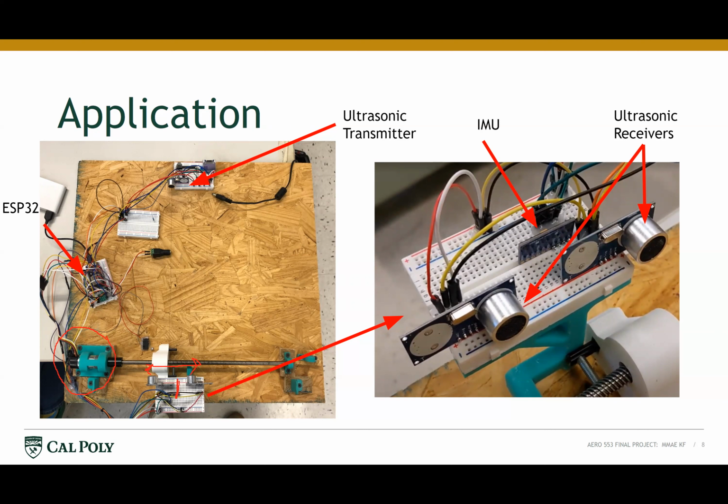And then the two methods we're using to estimate position, which are more realistic, like having a car driving down a road where you don't know the true position because it's not attached to a linear screw, are, one, acoustic positioning using the receivers here and the transmitter on the left here, which send out a pulse from the transmitter received at the receivers at different times. Using that time of flight, some simple geometry, and knowing this vertical distance, you're able to determine the position of the platform.